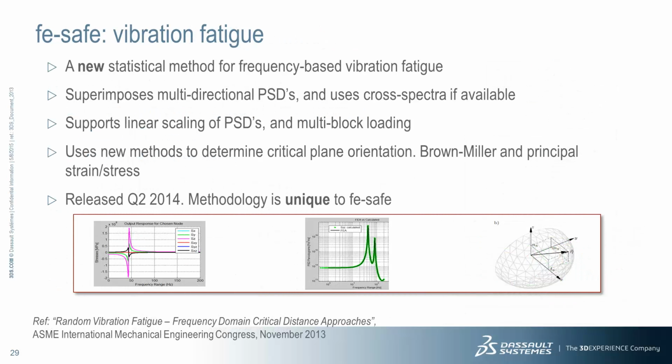For some components, loading may be specified in the frequency domain, and these components may also exhibit resonances with particular frequencies. We didn't feel that the existing methods were accurate enough, so we developed a new PSD fatigue methodology. Our new method allows you to incorporate multiple block loading and multiple PSDs and cross spectra for superposition in those blocks. Phase information can be used if it's available in those cross spectra.